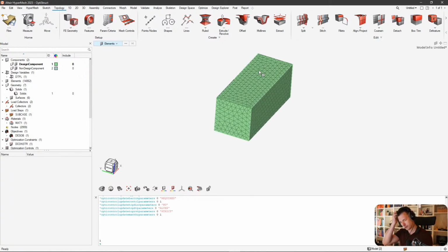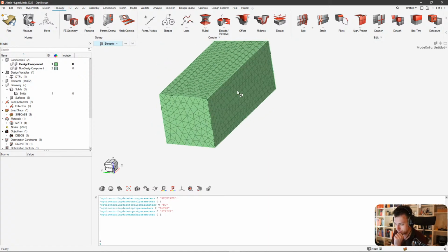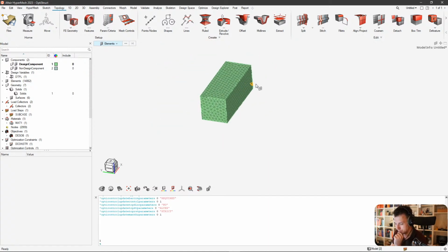Now I think about how we should proceed. I think it's good to do a full model and then split it and do a reduced model as well. Yeah, I'm thinking that makes sense. So meshing would be done for the full model, but I will be splitting it anyway, because it doesn't really change that much, but it makes life a lot easier later on.